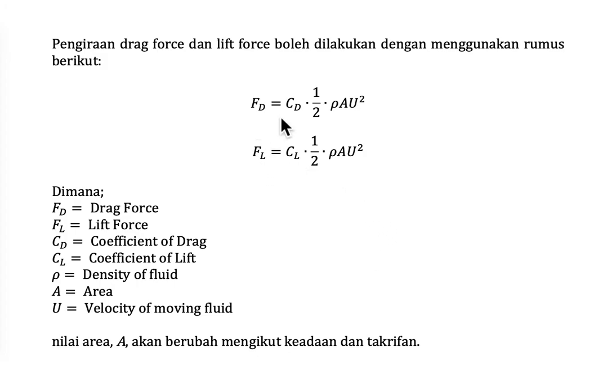So this is the common equation to calculate drag force and lift force. Drag force is equal to CD times 1 over 2 rho A U square, and FL is equal to CL, which is the coefficient of lift, times 1 over 2 rho A U square. So CD and CL are the coefficient of drag and coefficient of lift respectively.